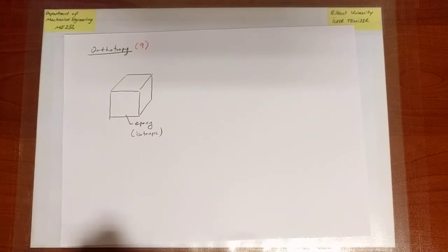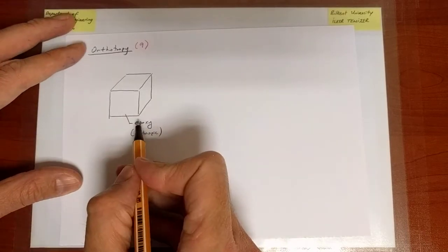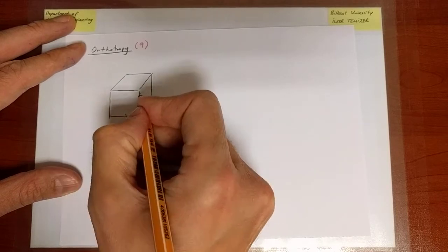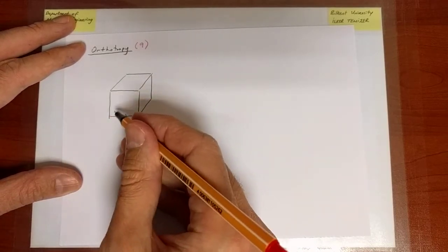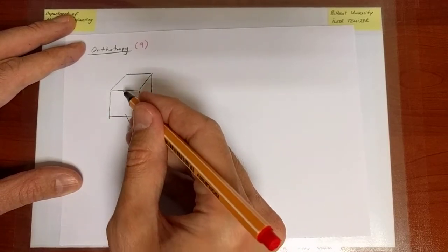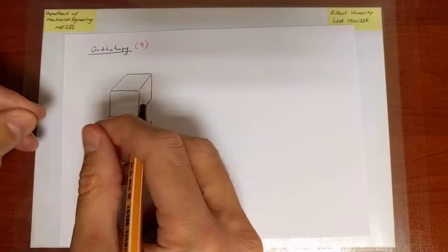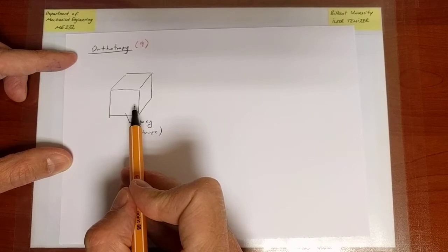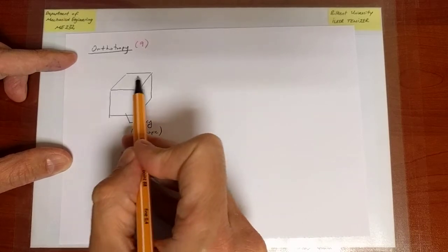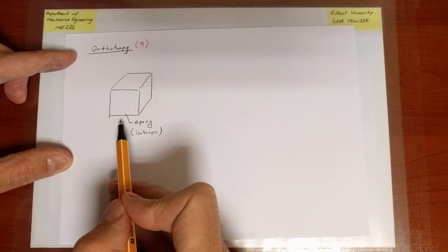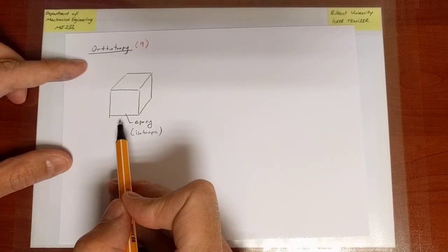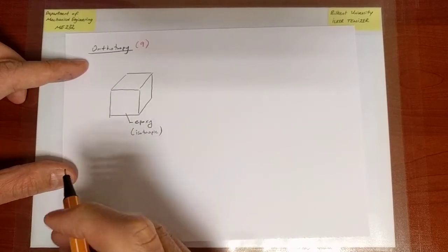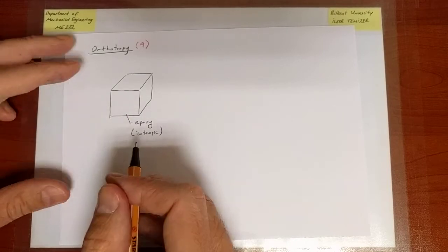because carbon fiber, for instance, is quite brittle. But if you were to put it into an epoxy matrix, that epoxy matrix would stabilize it from bending out of plane in the transverse direction. So it would also be stronger under compression. It would be stronger if it is combined with epoxy, and that's the idea of combining two materials when you make composites.